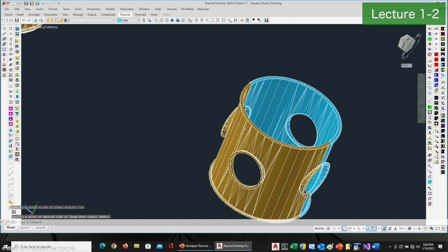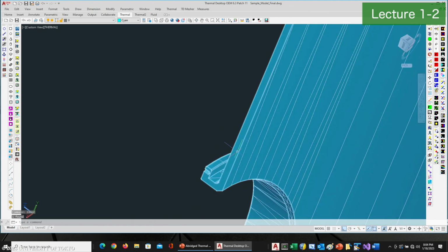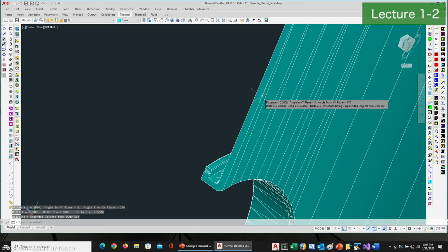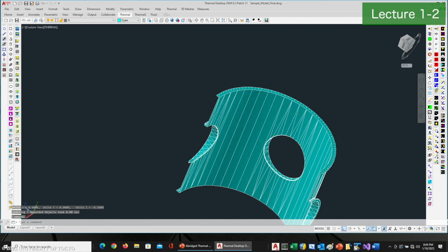Okay, now I've sliced it. I can delete this side, and now I've cut. I can look and see what the thickness is here. I could go distance from midpoint to perpendicular, and get a distance there that says, oh, okay, it's half an inch. So this lets me take measurements and build points on here.